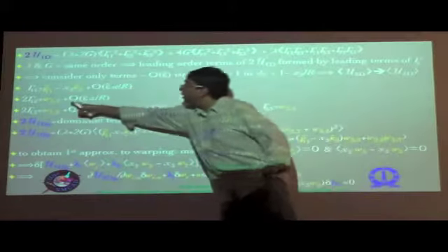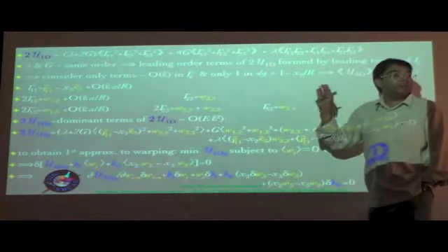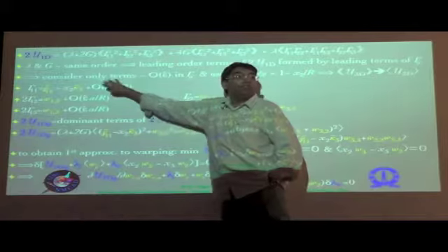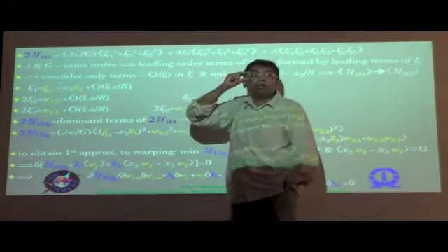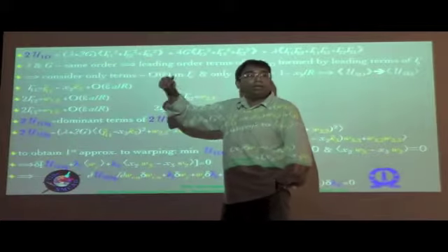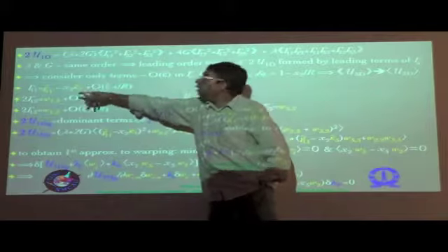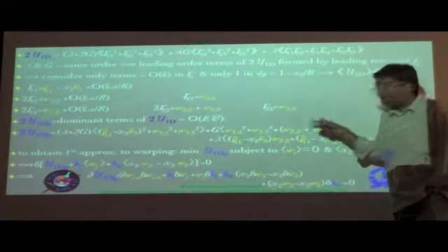They all appear either as a derivative with respect to 2 or the 3 direction, not even with respect to the 1 direction. There was a term here which was w1 prime, which dropped out because it was a higher order term, because w1 was of the order of epsilon hat times a, and prime made it epsilon hat a divided by L, and therefore it dropped out, right? So all derivatives of w are with respect to x2 and x3.